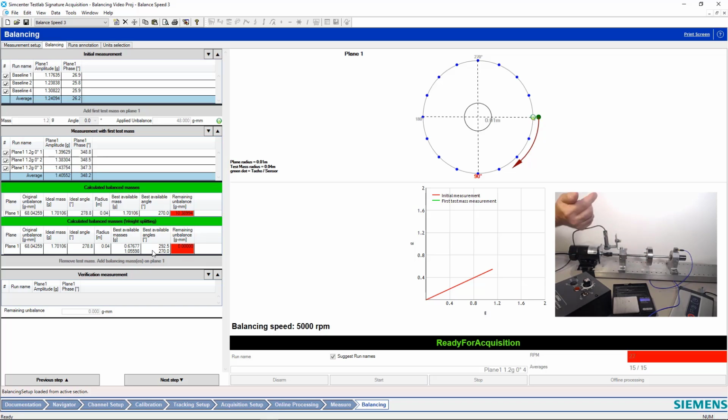Now that that's in, it's important, because you checked this, to remove the trial mass. That's right. In our software, we said that we were going to remove the trial mass, and that's what we need to make sure to do. Normally a part wouldn't be produced with a trial mass already in it, huh? That's right. And if you had to weld your trial mass on the part, you could keep it on. Oh, okay, that's good to know.